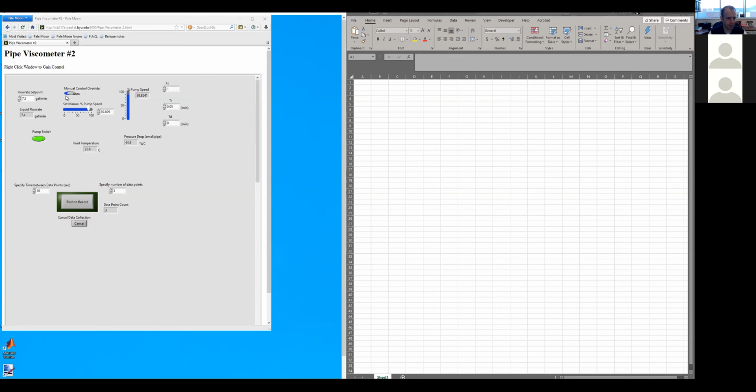And I'm going to put it in auto mode when it's close to that so that it will get down to about 7.2. And what we're going to do is read off the pressure drop. And now someone tell me what this "WC" is that's also applicable to your lab. Inches of water column. And why such a weird unit?